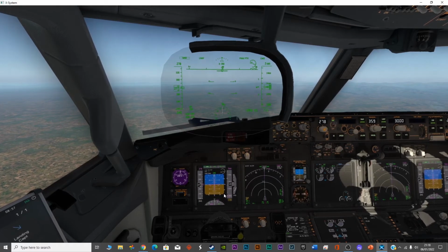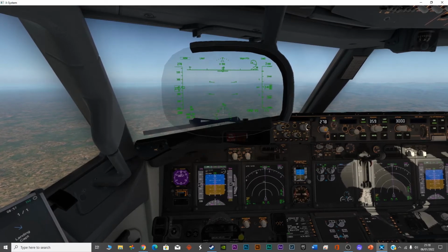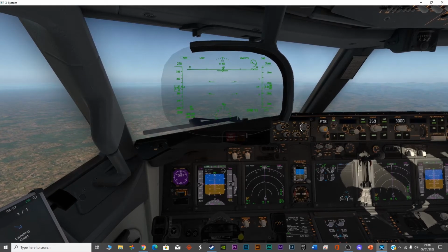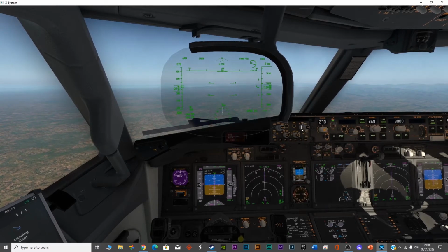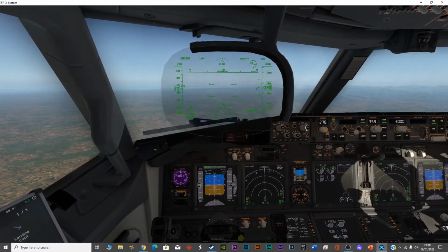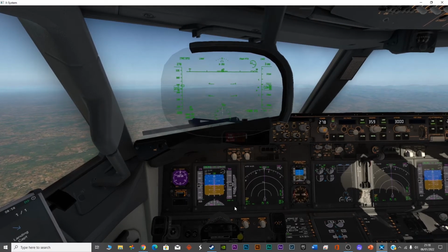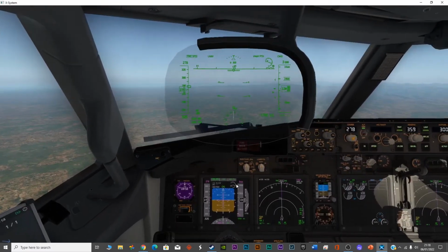Okay, now you can see this has turned yellow, so I will turn it to 1018. Let's change the units. Okay, and it's 1018. So I have also now set the barometric pressure for the altimeter. Now the altimeter will be giving me the right readings.